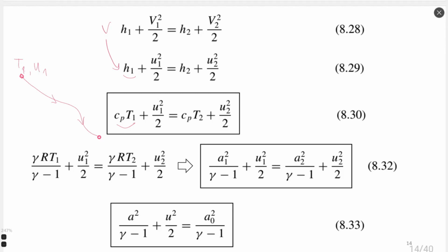But usually we cannot put all necessary sensors at this point, and there can be several reasons. Some sensor can distort the flow so much that you will not be capable of detecting the properties of the undisturbed flow. For example, you create a shock wave because you put too big a sensor inside, so the flow is changed definitely. You cannot take the previous parameters.